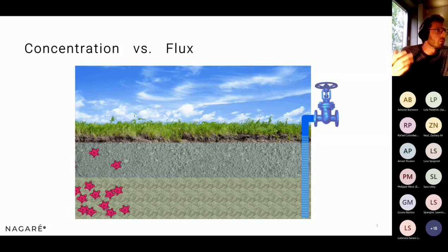So in this case of a really simplified aquifer with 2 layers, we can see that there is a lot of pollutants in the bottom layer and not much in the top layer. So we will logically focus the effort to treat the lower layer first, of course, to avoid all this pollutant ending up in the groundwater abstraction well drawn in the right-hand side of the picture.